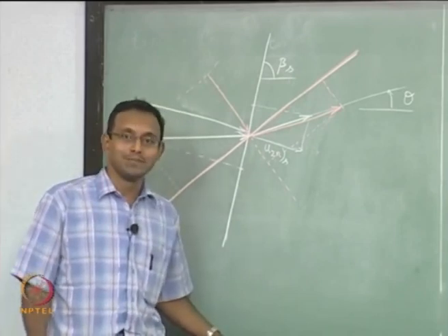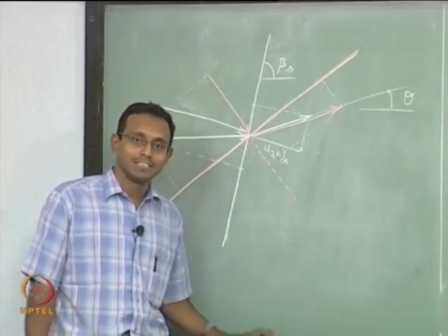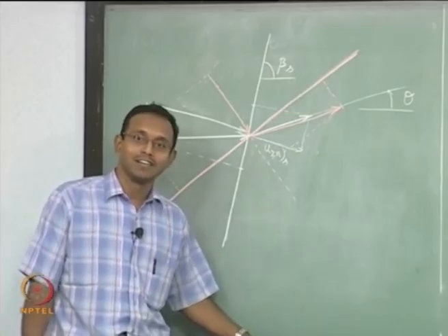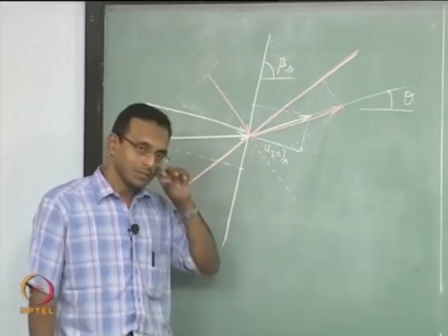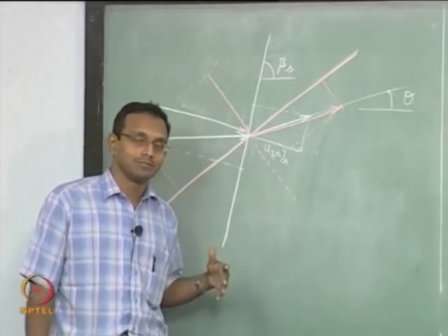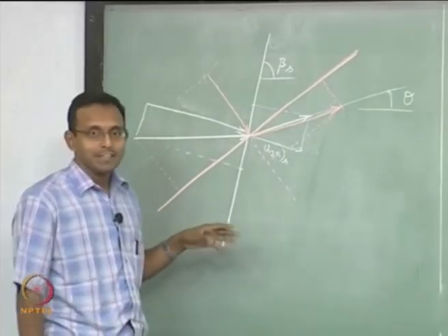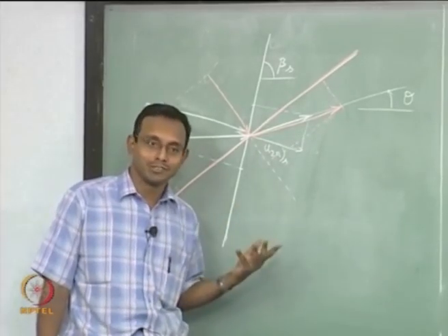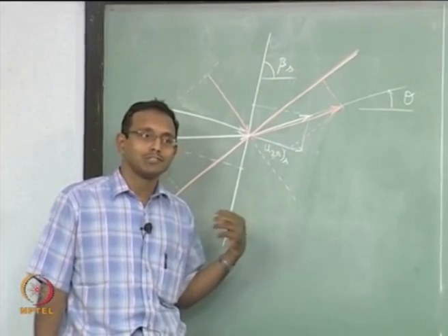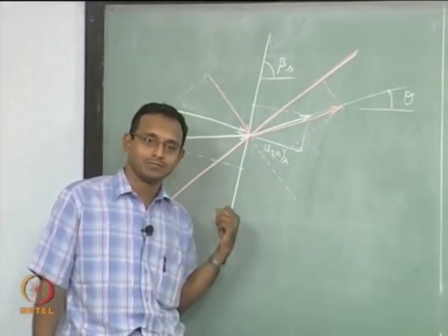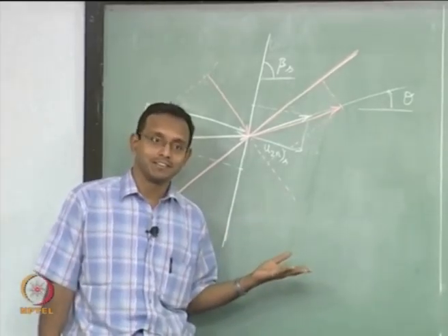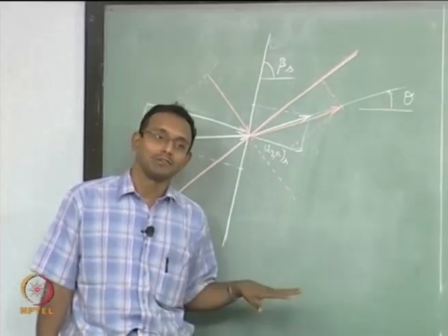That is the idea of stability here. It so happens that it has now been recently proved, recently in the sense it is last year or this year, that the strong shock solution is an unstable solution, while the weak shock solution is a stable solution. Because of that, if there is ever a formation of a strong shock solution, any small disturbance, noise, any small disturbance in the flow will throw it to a weak shock solution. Okay. That is why when we wait for long enough to form a steady stable solution, steady state, and we are looking at the problem, we will always see only weak solutions.